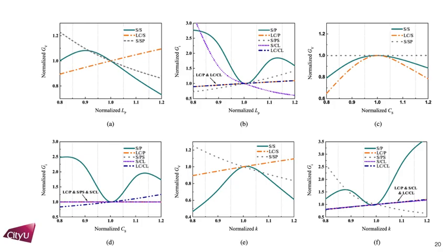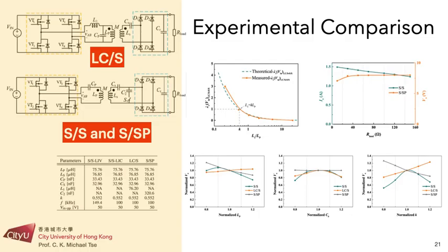in general. Okay, and experimental circuits also confirm the same understanding, that is the higher order circuits under appropriate choice of parameter range are able to produce circuits with much less sensitive performance against, for example, input voltage and variation in coupling coefficient and variation in some of the inductances or leakage inductances and so on.